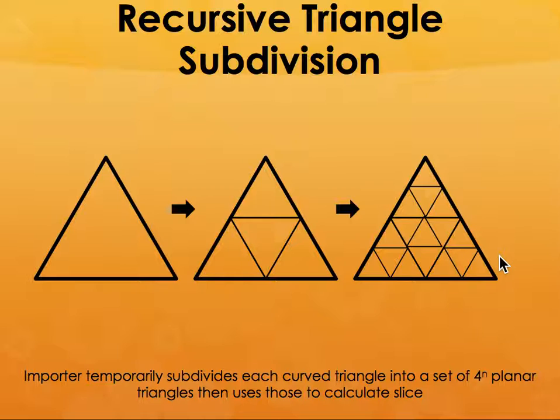So when you look at a simple case, suppose your software can build these kinds of rectangles and use that to fill space. This is not very accurate. So your final component is going to have a lot of surface finish issues, and you will have areas where the material has not been filled properly.